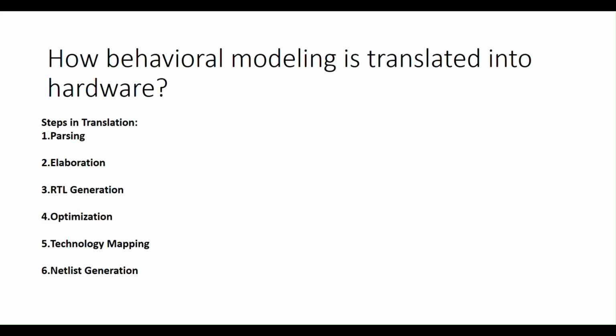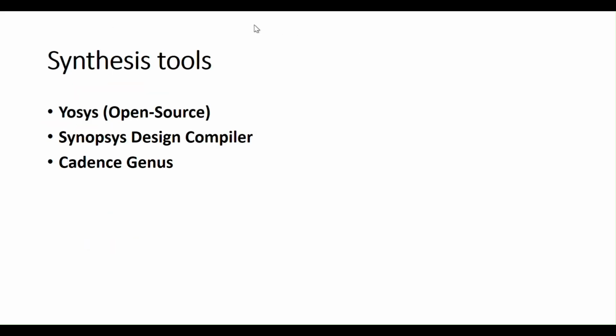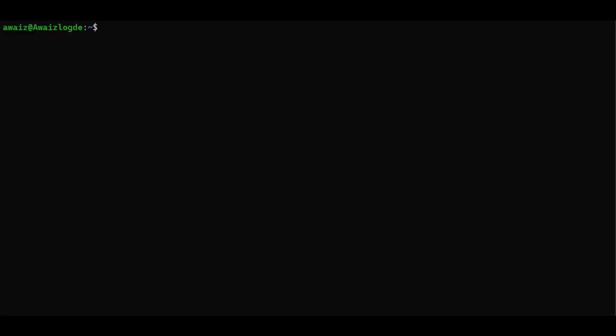There are some synthesis tools: Yosys, which is open source, then Synopsys Design Compiler and Cadence Genus. These are the industry commercial tools. Let us see how we can do synthesis in Yosys, the open source tool. So now we will do Yosys synthesis of that ALU.